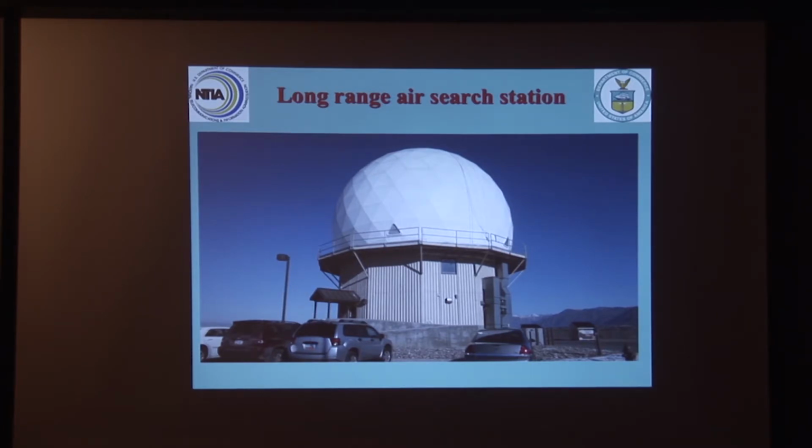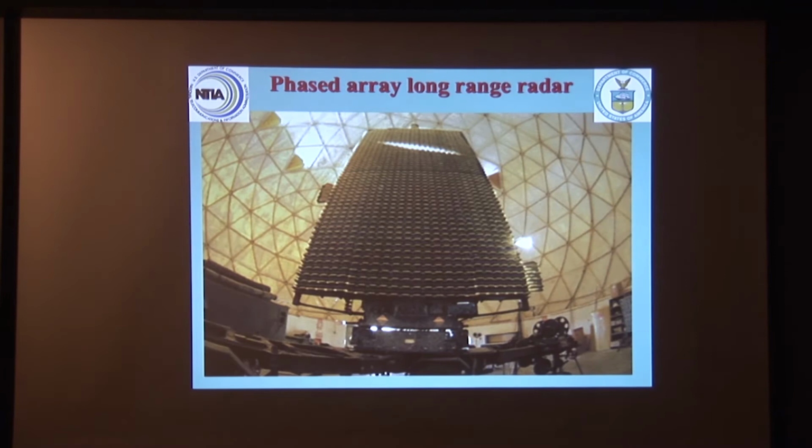What's this location here? This is at Hill Air Force Base in Utah. Yeah, nothing classified about that, nothing secret. It's perfectly out in the open. This is the TPS-59. I mentioned that a minute ago. Now, this is a 3D radar. It rotates mechanically about once every 10 or 12 seconds, but while it rotates, it scans a beam vertically, electronically like this, and it gets elevation angle information while it's rotating around. So it's a combination mechanical and electronically scanned radar system.